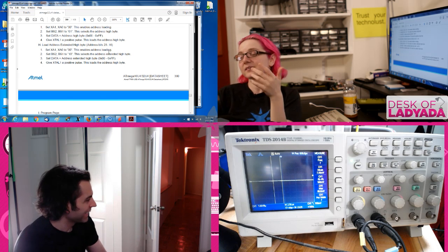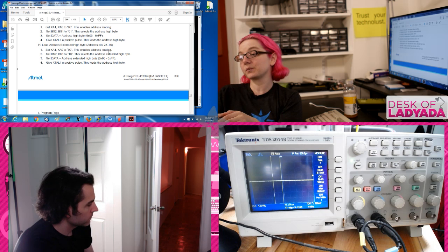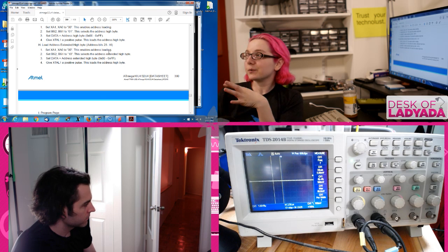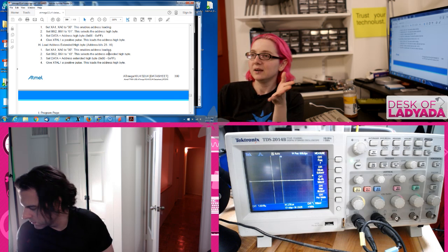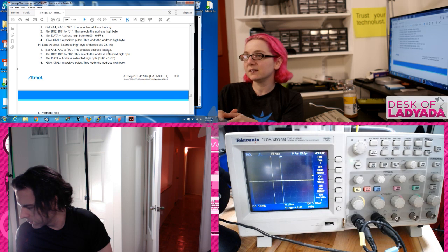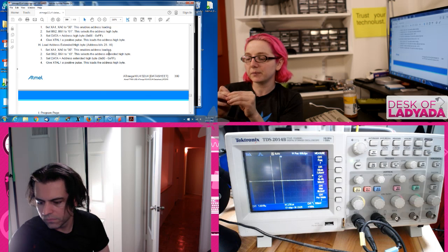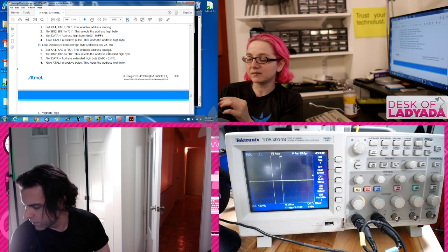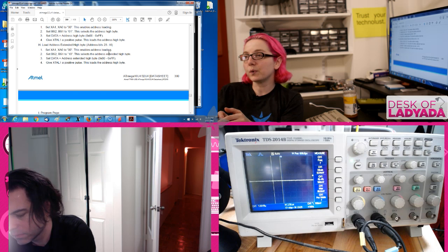I was talking to K-Town, because he's done so much stuff with the Cortex M0, and he's worked at companies that design chips with Cortex M0, and I said, hey, how hard would it be to make a bit banging Arduino that would bit bang SWD? And he said, you do not do this. Do not go down this rabbit hole. He said, let's check out OpenOCD, and you can use a Raspberry Pi or something with an ST-Link. So he kind of pointed me down this path. He's like, I don't know what the fastest way is, but you don't want to bit bang SWD. You end up rewriting OpenOCD basically, and there's no real way to do it.